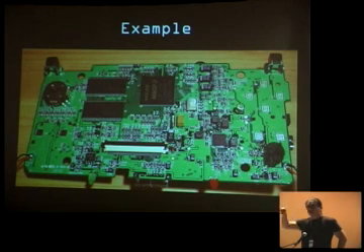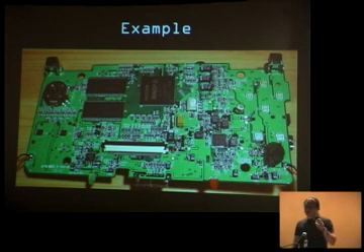And then the next thing you do is look at the package, and almost always, when they scratch off the top, it's a Xilinx CPLD or a PIC microcontroller, because those guys think they're badass and they got something cool inside. There are only so many footprints of PICs, and you'll see the ceramic resonator for the PIC and so forth. You say, okay, this guy's got a PIC, it's probably this series, and then you can hook up the pins where you think they might pull out the serial code, whatever it is. So typically, you can look at other cues on the board to figure out what's going on. In the worst case, you take the chip off, send it to Memphis, give them $100, and it comes back with no plastic on it, and you just read the manufacturer's labels right off the silicon, so you know what it is.